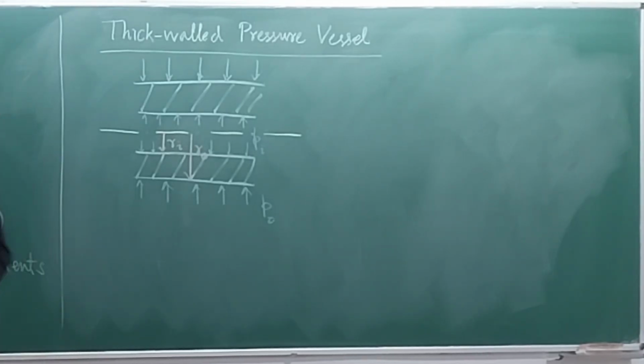Now, you are just about to learn something extremely important. You are already familiar with it, and that is the condition of plane strain. I have mentioned this earlier. When you have plane strain within the xy plane, then you have epsilon zz equal to 0, epsilon zx equal to 0, and epsilon zy equal to 0. When you have plane stress, then you have sigma zz equal to 0, sigma zx equal to 0, sigma zy equal to 0.